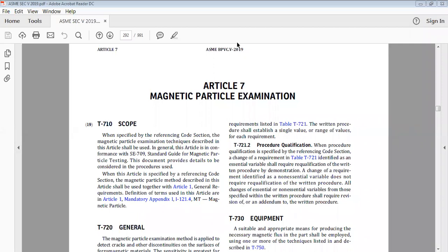You know flux density means the number of lines of force per unit area. And what is magnetic field? Magnetic field means the total number of lines of force. The total number of lines of force is very difficult to measure without breaking the magnet. So here we use a Gauss meter to measure flux density. So in a particular area, how much magnetic flux density is there. We generally get readings like 10 Gauss, 15 Gauss, 20 Gauss, 50 Gauss.